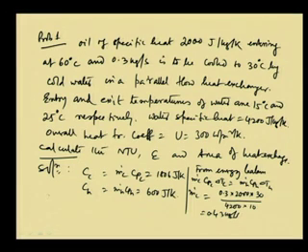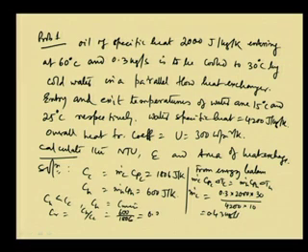So, Ch is less than Cc, and Ch is C minimum, the minimum fluid. Though we have done the evaluations based on minimum fluid for cold fluid, here the hot fluid is becoming minimum, so we are changing this. Now, Cr is equal to Ch by Cc, which is 600 by 1806, and that is 0.33.